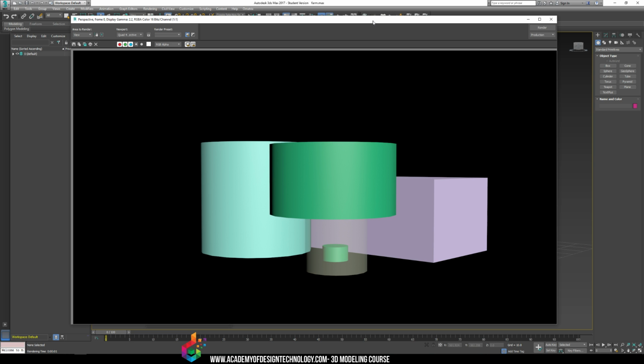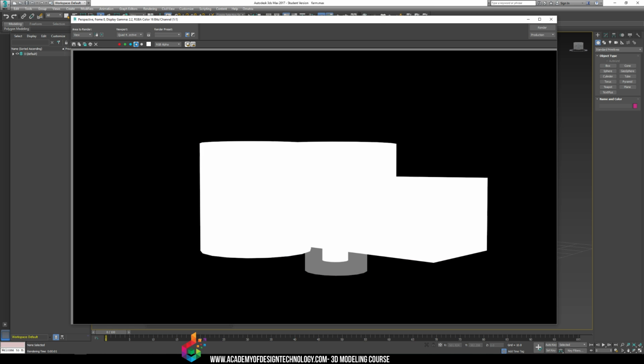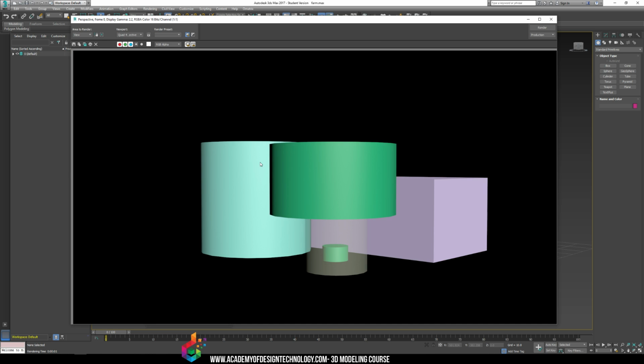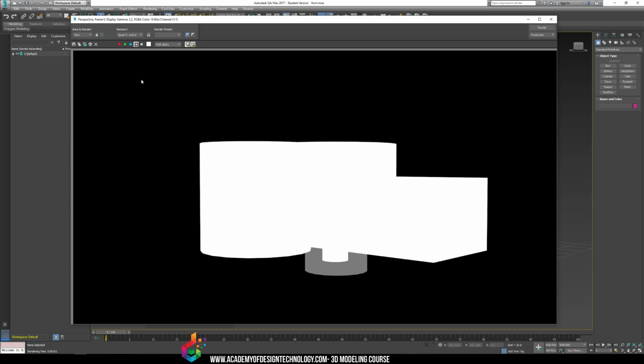Anything that's in black currently inside 3D Studio Max is actually transparent. And you can click through the different alpha channels here to see what's rendering and what won't. This is an alpha channel, kind of like how Photoshop would view an alpha channel. The white is considered visible, the black is considered invisible, and anything gray or in between means it's semi-transparent. So you can see, because I changed the visibility of my ray here coming from the alien ship, my tractor beam, it's actually semi-transparent also in the alpha layer, which is great. That's exactly what we want.